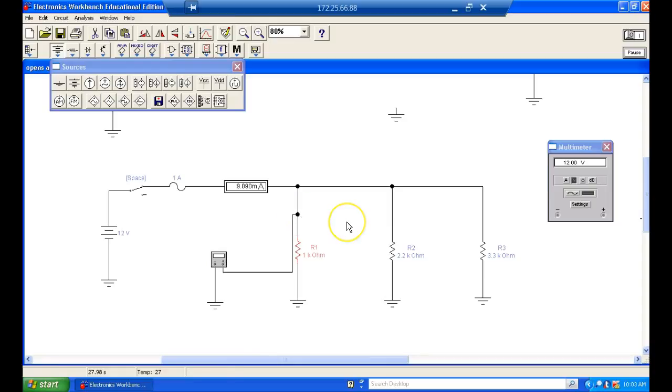Opens in parallel circuits are harder to find. In a series circuit, it's real easy to find because in a series circuit, it drops the applied voltage. In a parallel circuit, it's going to drop the applied voltage whether it's open or shorted, right? I mean, whether it's open or not. So notice I still have what? Still have 12 volts. Still have 12 volts here, still have 12 volts there. So what's changed is the amount of current flow in the circuit.